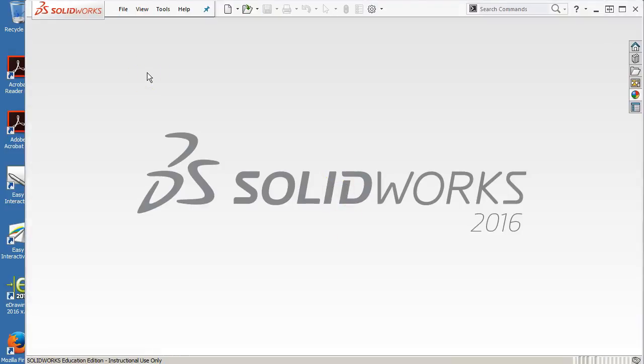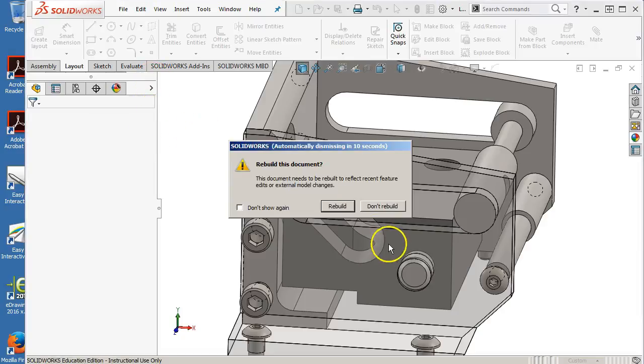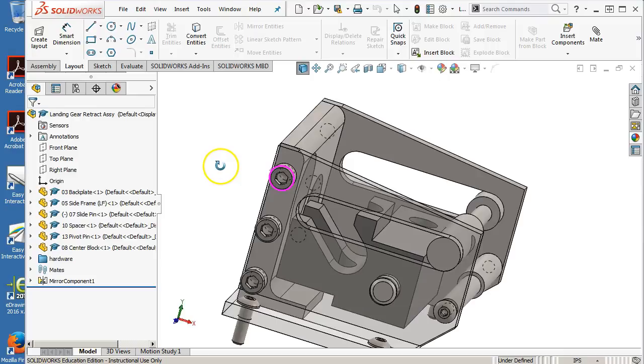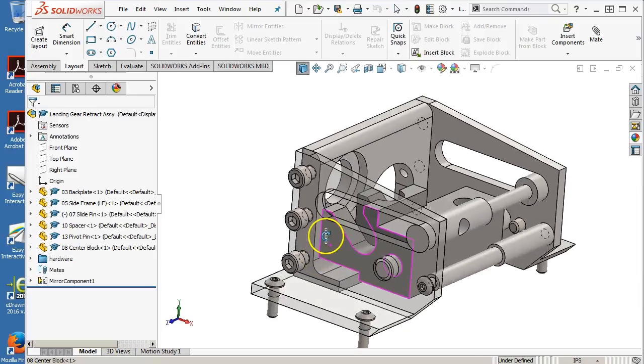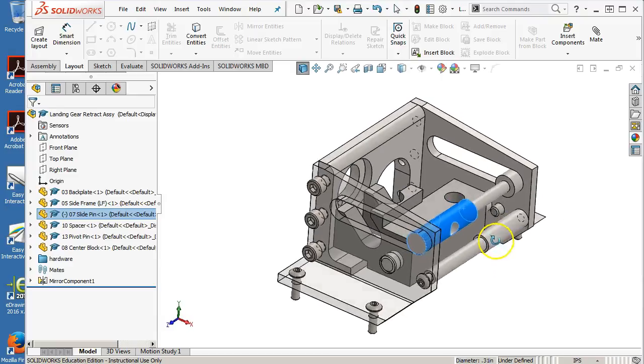The interference check is more just in that 2D space, or in those two axes that we're moving in. If you want to do full-up interference, then we're going to need to look at the geometry. So I think one of the issues was this radius was larger and it contacted the endpoint, and we're not quite moving through all of our same motion.